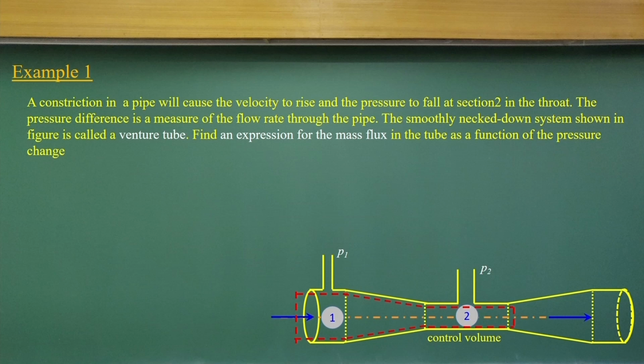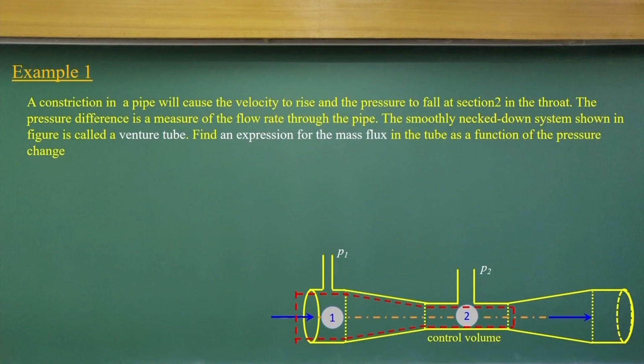Here we will apply mass conservation and Bernoulli equations. That is all. We are not going to do much here. But I always encourage you to sketch the control volumes as well as draw streamlines. After drawing the streamlines, apply the Bernoulli equation for the two points. Always highlight what the assumptions behind that are. What assumptions you have put in should be highlighted before solving any fluid flow problem.